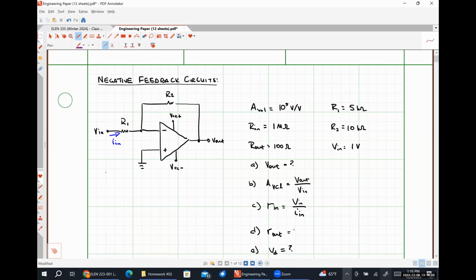We'll see that, realistically, what we have here is this R1 in series with an open circuit. And so that's why we only see R1 by itself as the input resistance. When we're looking in through this guy, we're just going to see a huge resistance. Technically, it's going to have a value because we have a finite input resistance that we're looking into, but it's going to be astronomical. I don't want to get too far ahead. I'm talking like three classes later in Electronic Circuits 2. We're going to explore those relationships in a whole lot of detail.